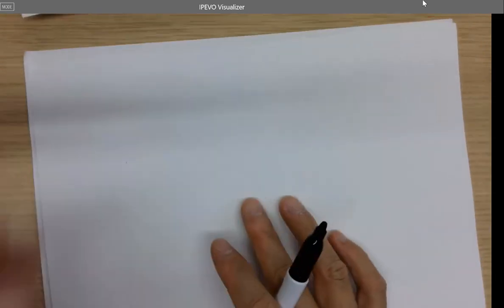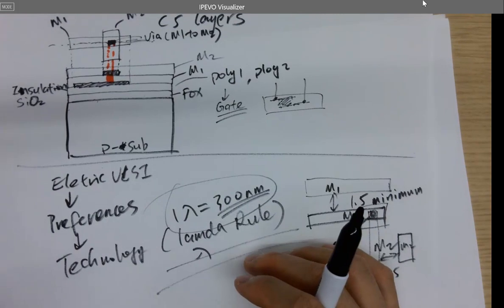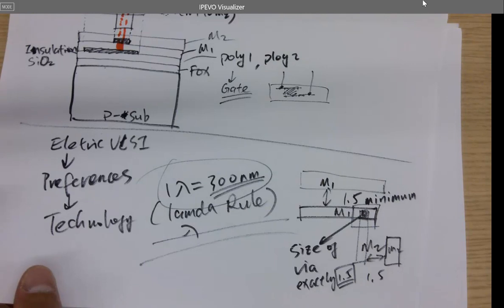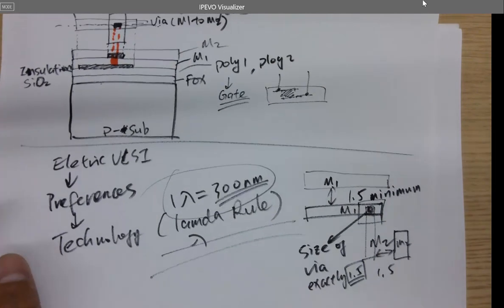There are probably, just for the C5 layers, hundreds of different rules to define all the spacing and size of the traces. Nobody knows what they are. So you just use the EDA tools. Whenever you move them closer, you see an error. Then you keep them more apart from each other. That's it. That's how to do it. Nobody will remember all the rules. It's okay.